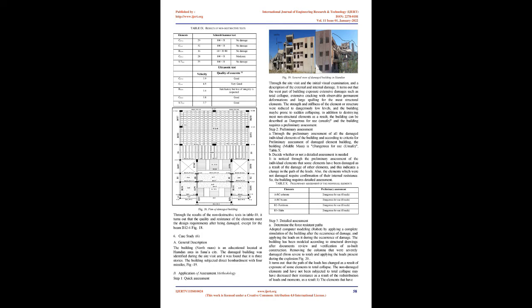Step 3. Detailed assessment. A. Determine the force-resistant paths. Computer modeling, Robot, was adopted, applying a complete simulation of the building after the occurrence of damage, and applying the loads on it during the occurrence of damage. The building has been modeled according to structural drawings after documents review and verification of as-built construction. Removing the columns that were severely damaged, from severe to total, and applying the loads present during the explosion.